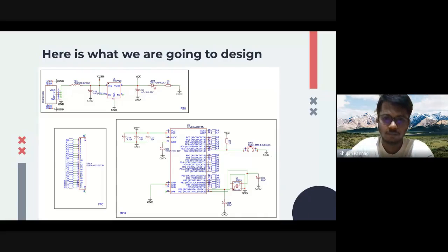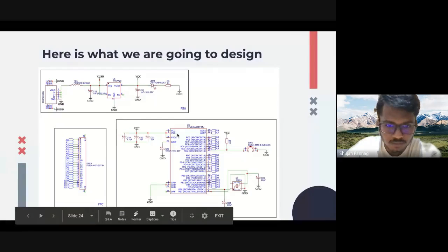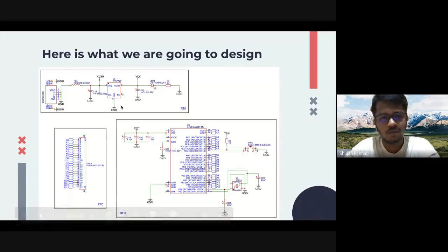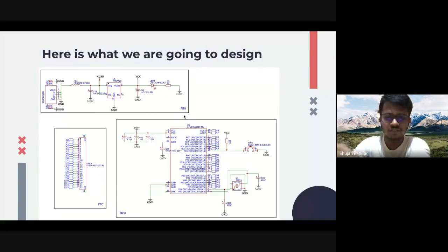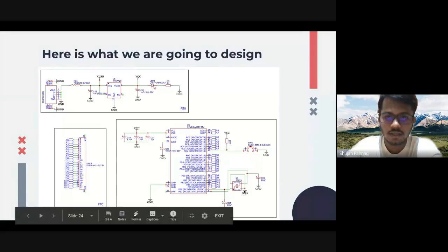So PC6 reads 0, and the interrupt is called for the reset of the MCU. So that's this part, and this part is done. This is just ground. Any pin that you're not using, it's good to put a no connection flag, because it will be really helpful for the DRC checker to see if there are any issues with your PCB.